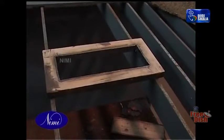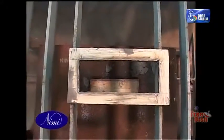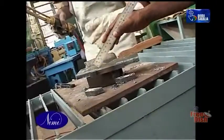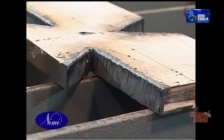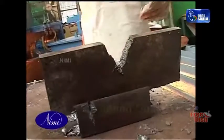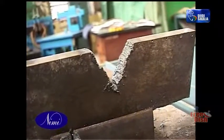After cutting, the nozzle gets heated up, and it is always safe to dip it in water before beginning the next exercise. The quality of an oxy gas cut is judged by a few characteristics. A satisfactory oxy gas cut shows almost smooth sides. A grooved or rough surface is a sign of poor cutting quality.